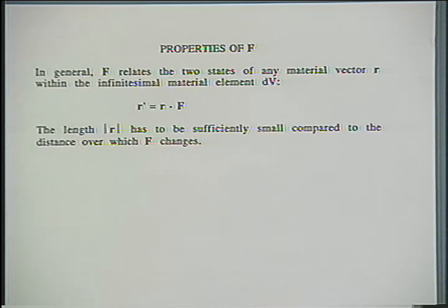So F contains only, from our motion, remember motion was deformation or strain, plus translation and rotation, and now we don't have the translation included anymore. F gives us only the rotation and the deformation, or the length change, of this material vector. So it's already going in the right direction. We want to get rid of translation and rotation for the purpose of calculating the stress.